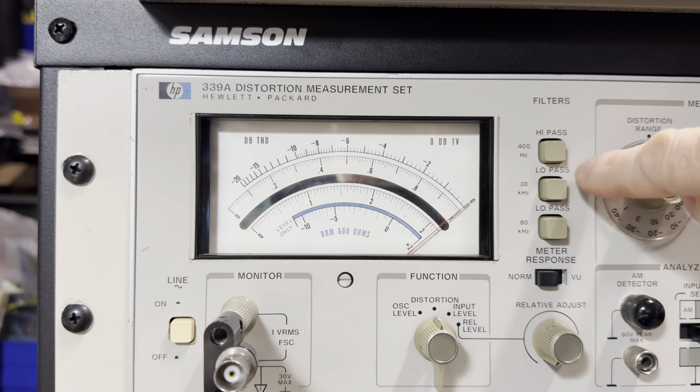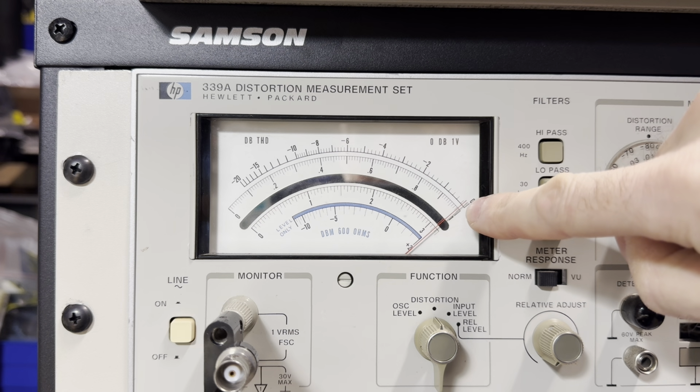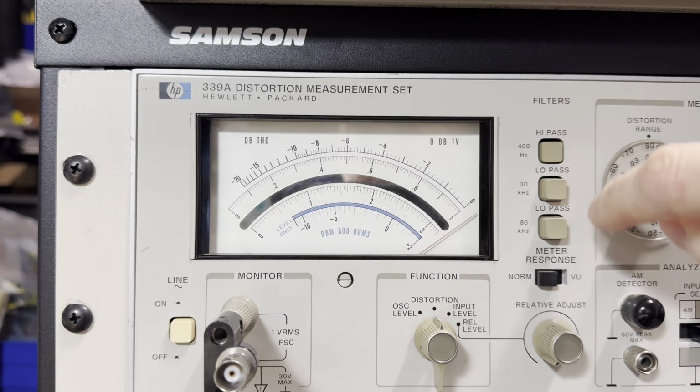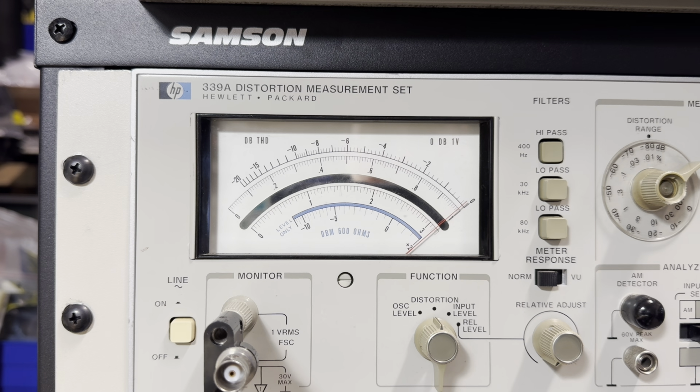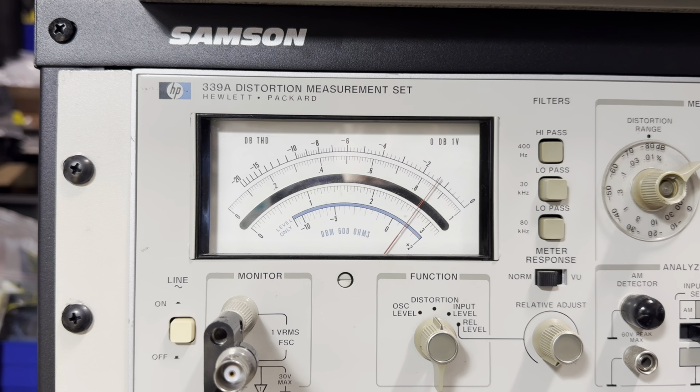Now let's see what we can do about the noise level. If we take out some noise, does that lower our measurement? See, now we've actually had a little bit of a noticeable change there, whereas we were right here just barely in the range. Now we've gained about 0.2 dB of measurement there, removing noise. We can go further and remove some more noise, some of the higher frequency components, and we see now we've had even more of a change, almost 1.5 dB of signal.